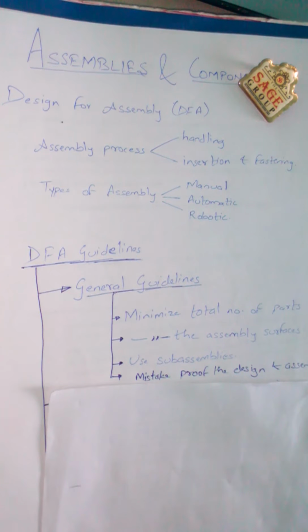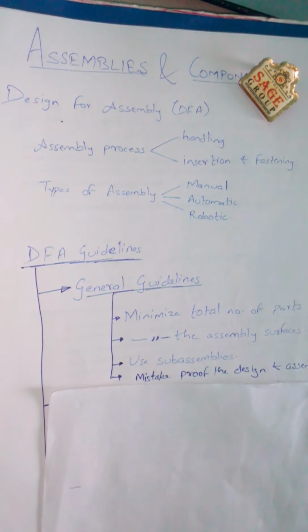An important goal in design for assembly is to ensure that the assembly process is unambiguous so that the operator cannot make mistakes in assembling the components. Components should be designed so that they can be assembled in one way. The way to orient the part in grasping it should be obvious and it should not be capable of being assembled in the reverse direction. Orientation notches, asymmetrical holes and stops in assembly fixtures are common ways to mistake proof the assembly process.